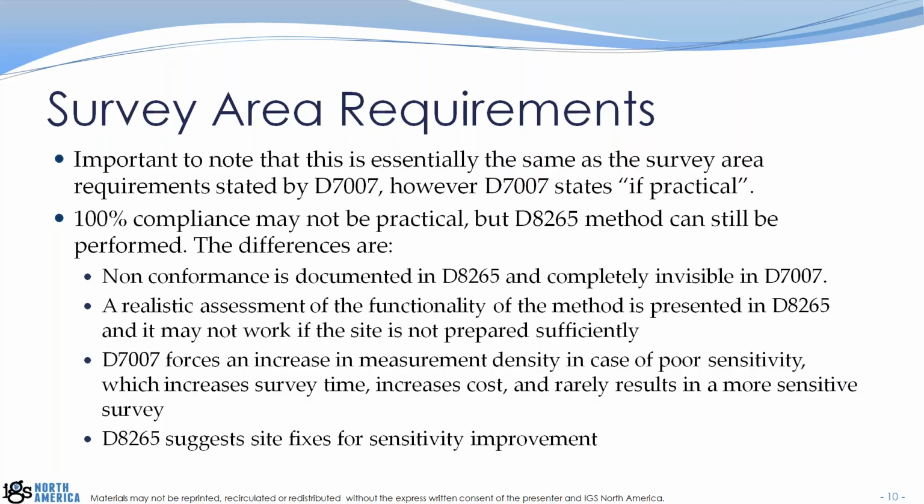So yeah, it's a little bit easier to see a hole when you're a little bit closer. We all know that. But when site conditions are poor, you can measure every square inch and not see a hole. I've had a site that had extensive damage. It actually had a perfectly clean isolation trench, but extensive damage everywhere. And I could be right on top of a hole, touching it, and not sense it at all. Because the current has to at least be contained somewhat in the facility. If not, it just pours out like a sieve, and you can't measure a discrete location where it's exiting.